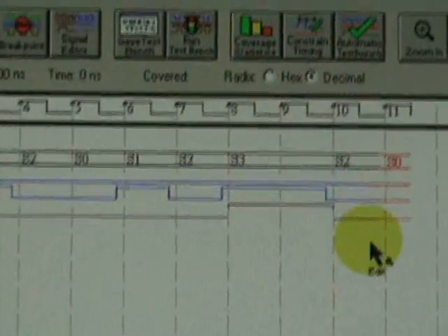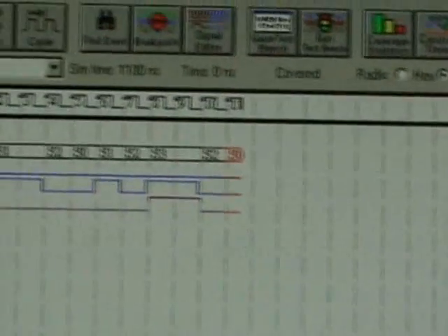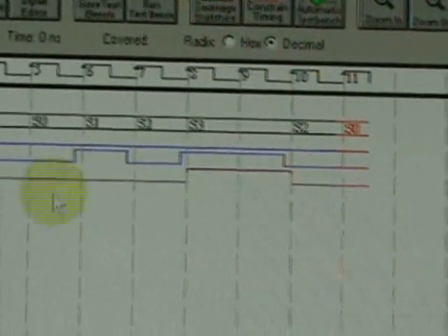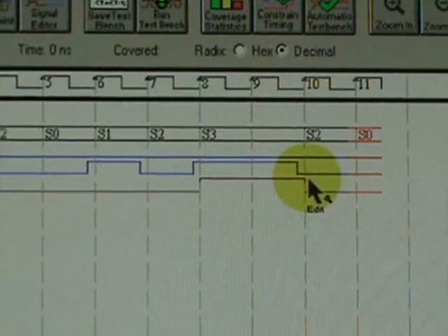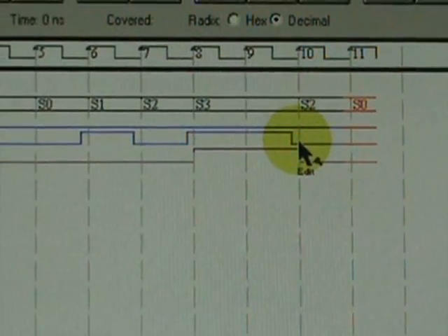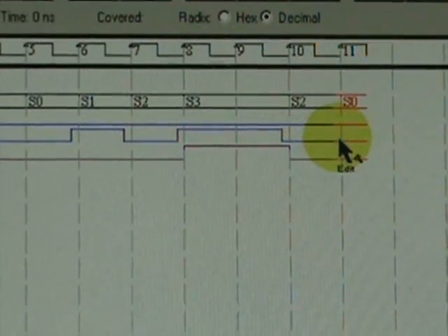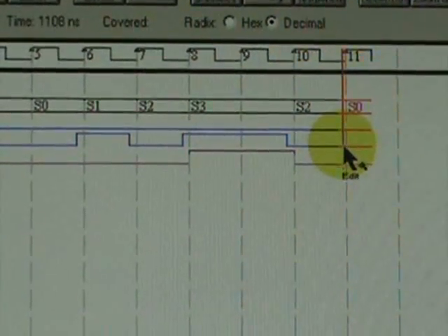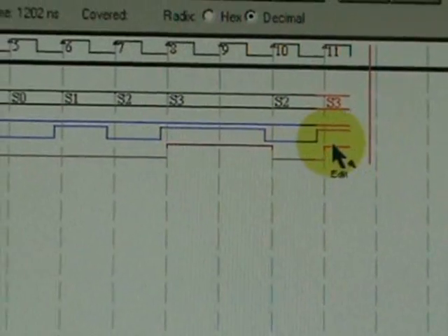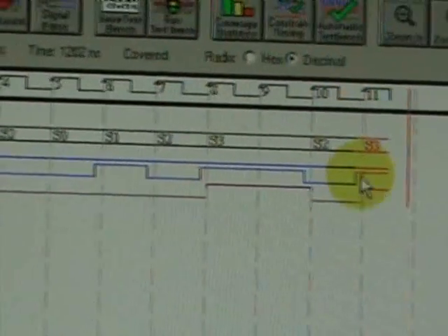If we want to add some more to it, we can manually do it, of course. Let us, well, that's probably good. To continue this manually, since the last detection is 0 in, and we would like to detect 101, let us try to supply here a 1 for X. So click this X here, double click there, and notice the output starts up, because this is 1, 0, and then 1 here. So immediately we have an output here.